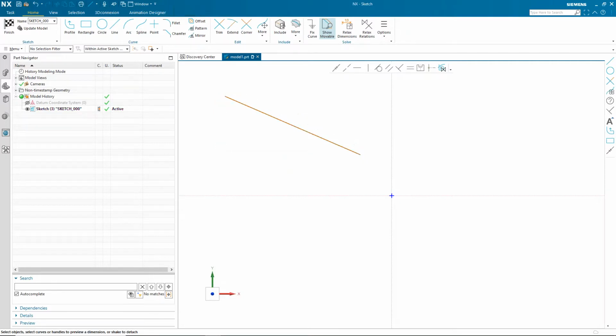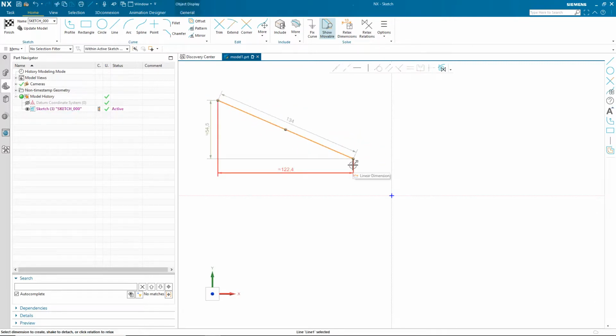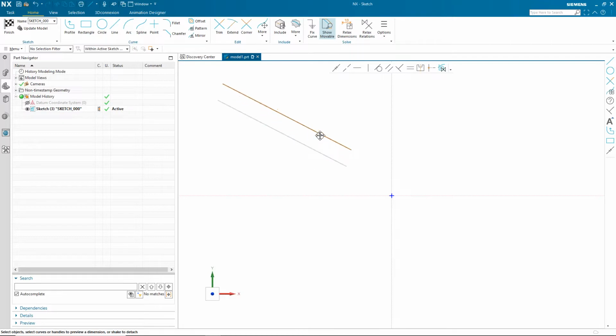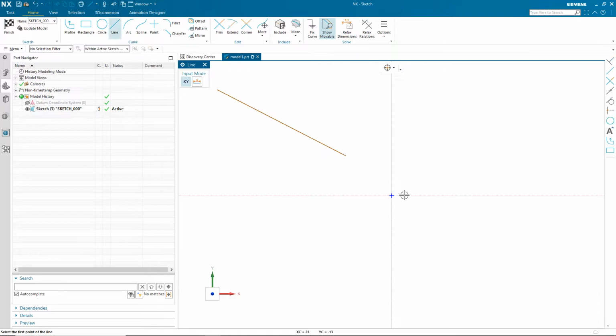But the other thing is to think about how geometry works. So I said if I pick the line and hold down, I can drag it around. If I pick the endpoint and drag, I don't get parallel, because with a point I can pivot around the other spot. So what you pick does matter with the new sketch when you're creating stuff to get it to work. What I wanted to show first is how some of the make commands work and a few of the other things.